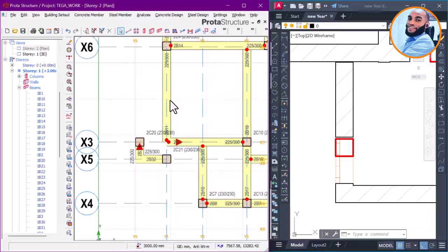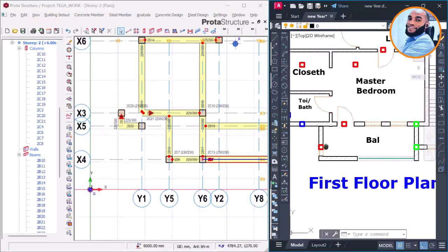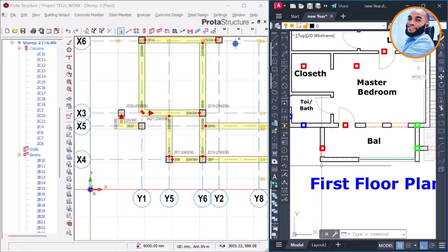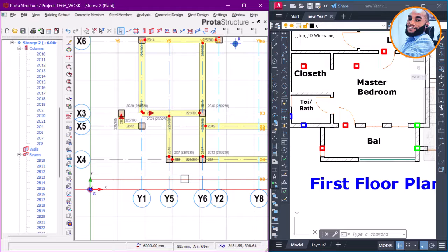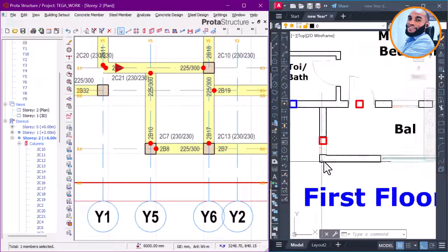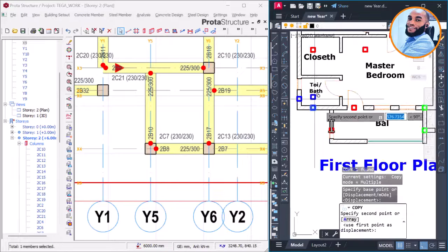That's fine. Again, that means this column here is meant to shift because there's a cantilever. Can you see that cantilever here, which is our ghost line, our ghost grid here? So right now we'll move it to this edge. So this column here will move. Let me just pick the moving column here. This column here we have to move to this place.